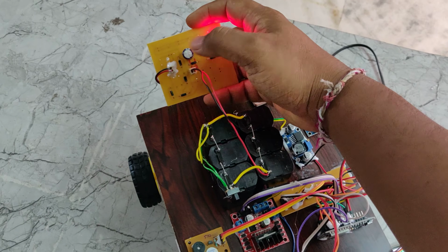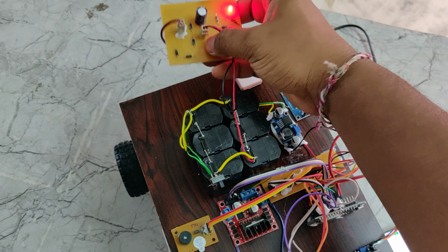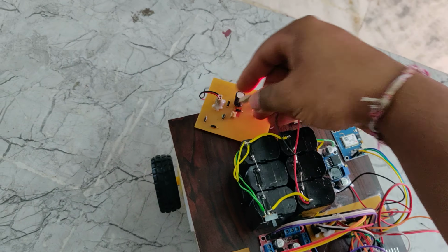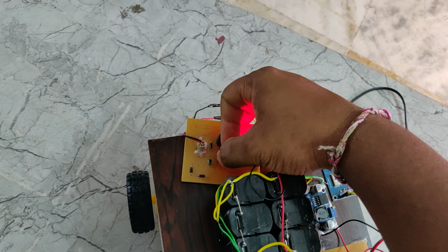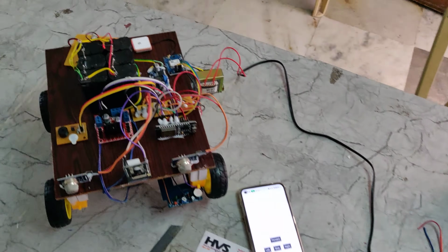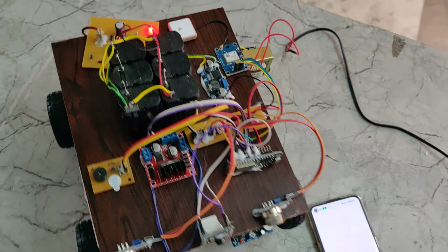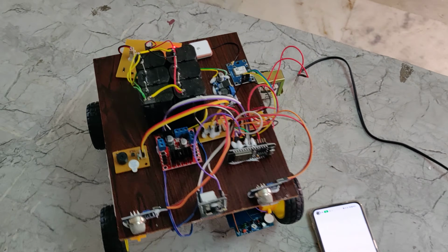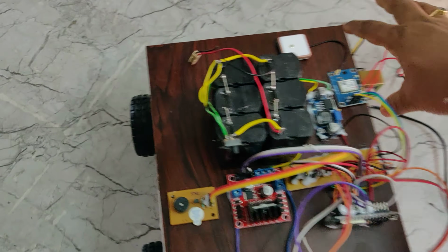To charge a battery pack, you just connect the battery at this 2-pin slot, as we have shown here. Connect this, and now power the supply to this transformer with 230 volts AC input. Now the charger is on, as you can see from the indicator light. We should keep the battery under charging for the mentioned duration. Once the charging is completed, you can just disconnect this. And now let us check the demonstration.